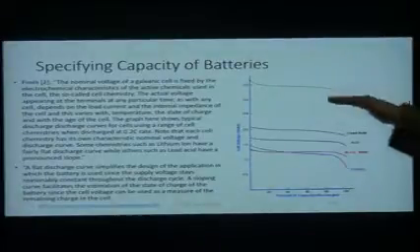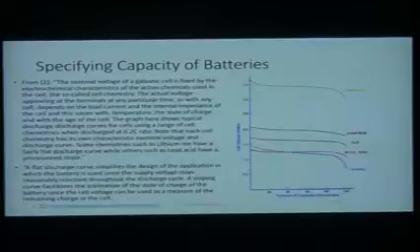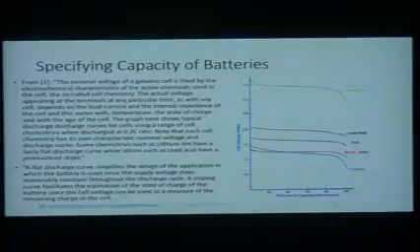But you also have to design, or someone has to design the load so that it can work with the battery as its voltage changes. And you see that these voltages are not constant. Some of them are flatter than others. The lithium ion is pretty flat at about 4 volts. The lead acid has a little bit more of a slope, but whatever you engineer the electrical system to do, it has to be able to accommodate a drifting voltage.